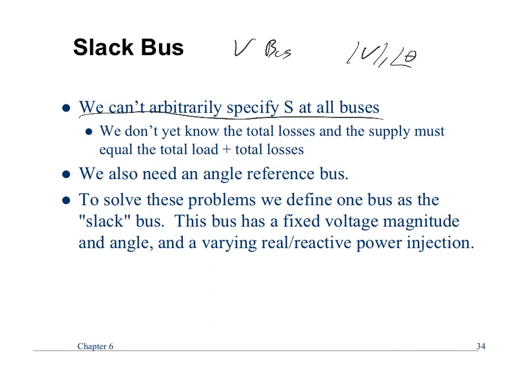So you created a fictitious bus, but in the real world, they didn't actually have one? Well, I'm just saying, from the standpoint of what I did with PSSE, yes, you make your own swing bus. That's just a bus sitting there on a system that's not really there.